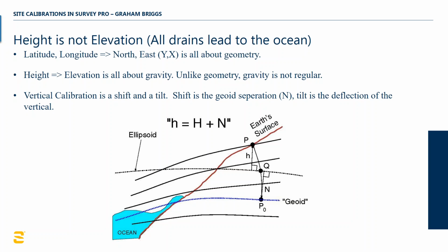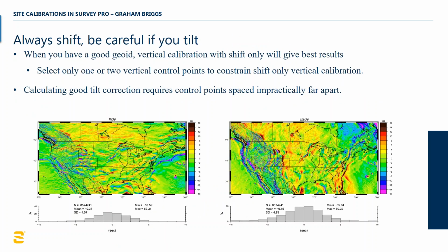And the lines representing different surfaces of gravity are also not parallel to each other. And again, because gravity is based on the actual distribution of masses within the Earth, which is more of an organic thing than a regular geometric thing, you get these differing lines of potential gravity energy that will get water to flow downhill. So let's go to the next slide, and what I want you to picture on this slide is, let's talk a little bit about the geoid.